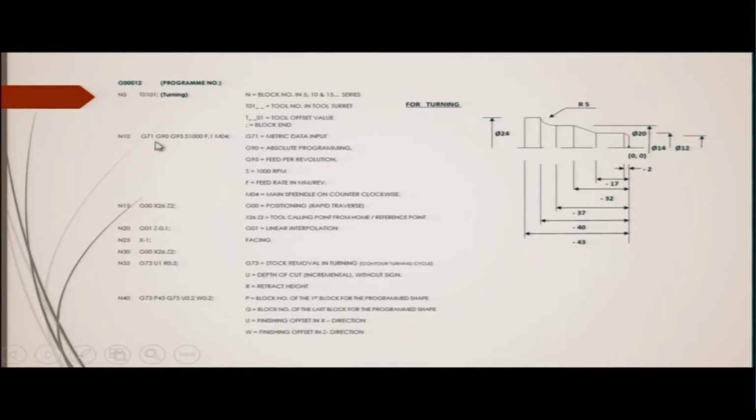And all of these codes are available in the table, and what each code means is given in the table. So, therefore, you have to just find out how the tool has to move initially, okay. That will be your decision, and accordingly you put that path or the pattern of movement of the tool in terms of those codes which are already tabulated.